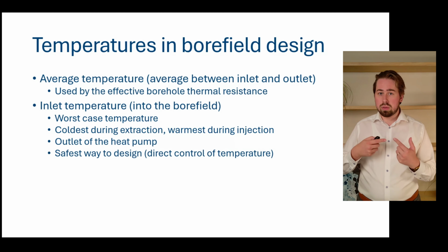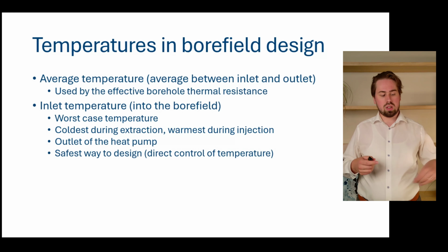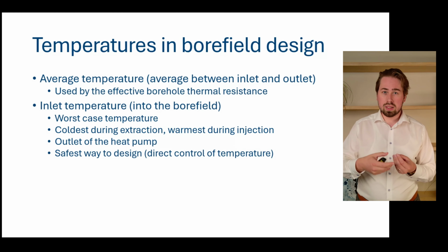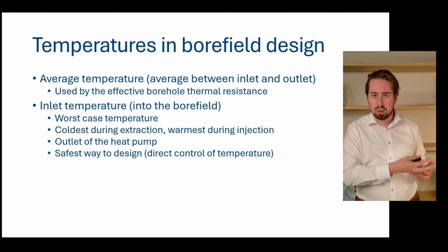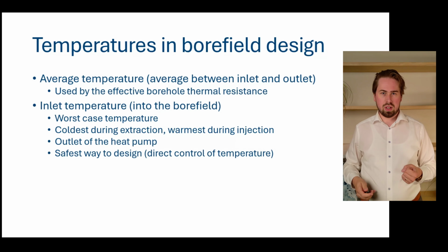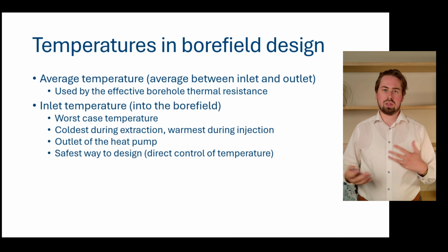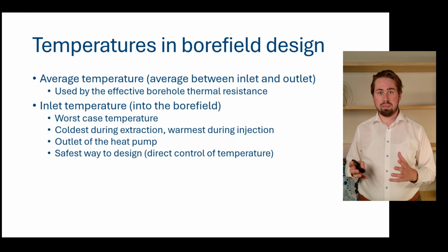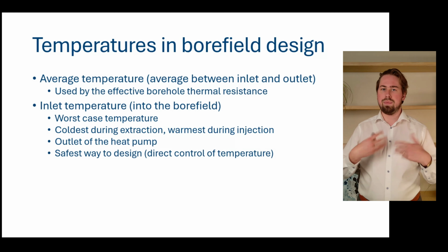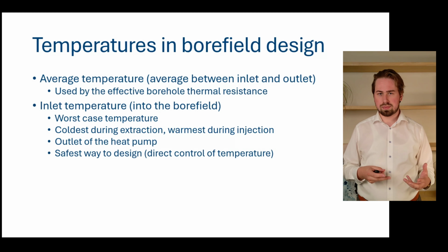And the same during injection when we're cooling, and the fluid comes out of the ground, the heat gets transferred to it, it warms up, cools down the building or the process, and this warmer fluid goes back into the ground. So basically, when you're talking about the inlet temperatures, these are the worst case temperatures. They're always the coldest during extraction, heating, and the warmest during cooling or injection.